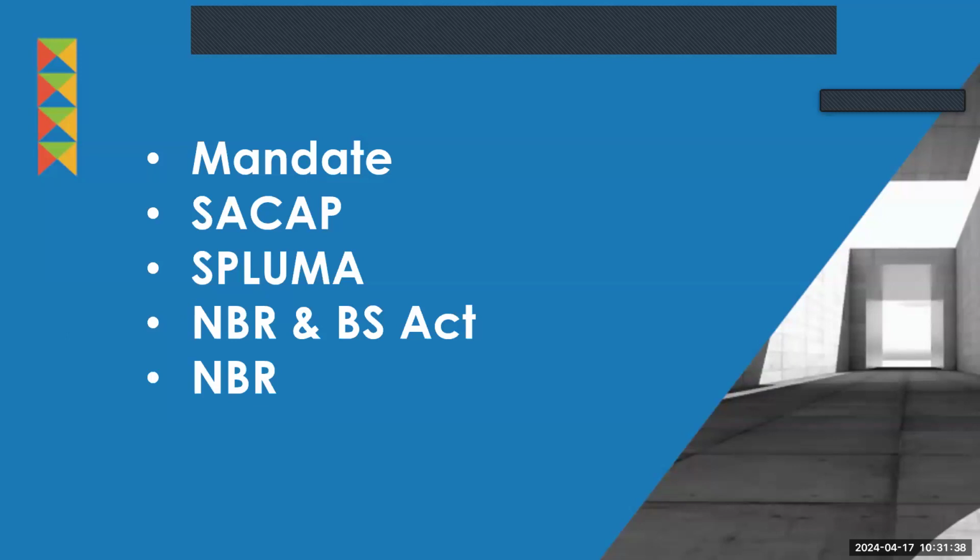There are a few regulations, especially in Part A of the National Building Regulations, specifically requesting certain things to be on a building plan for us to submit and to get it approved at the local authority. And then I'm going to end off with a few things out of SANS 10400 Part A, especially I think it's Form F1. That's a voluntary form, but that will assist us in making sure that when we submit building plans to a local authority, we indeed comply or have captured everything on our building plans that we need to.